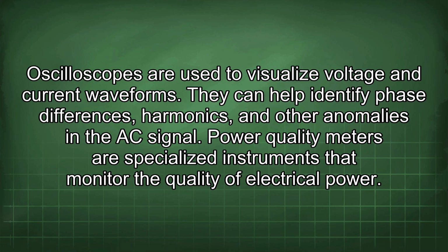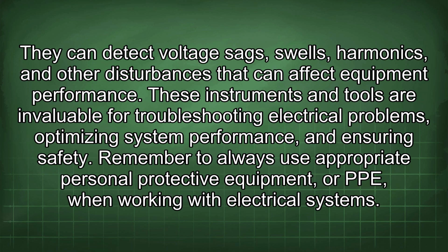Power quality meters are specialized instruments that monitor the quality of electrical power. They can detect voltage sags, swells, harmonics, and other disturbances that could affect equipment performance. These instruments and tools are invaluable for troubleshooting electrical problems, optimizing system performance, and ensuring safety.